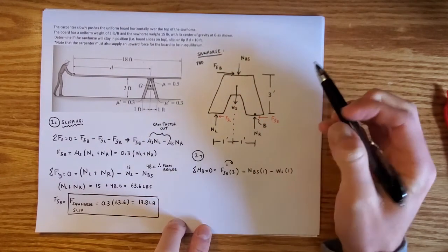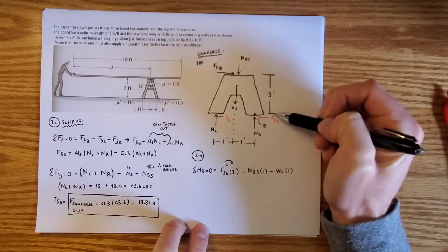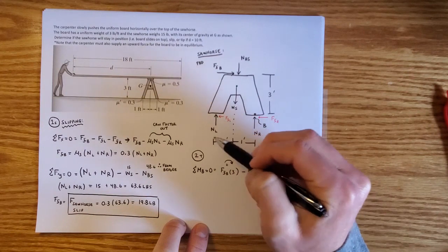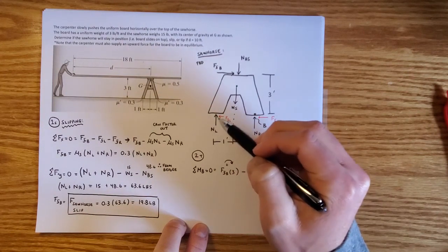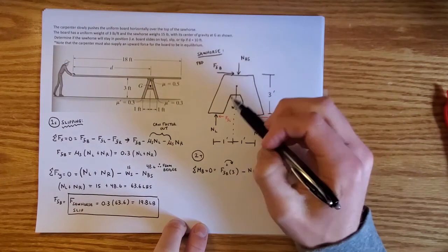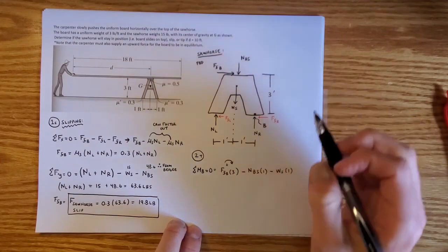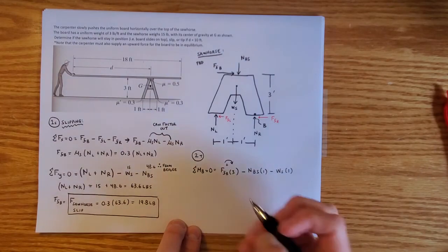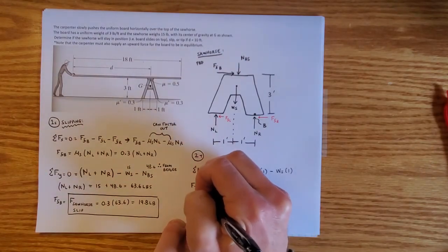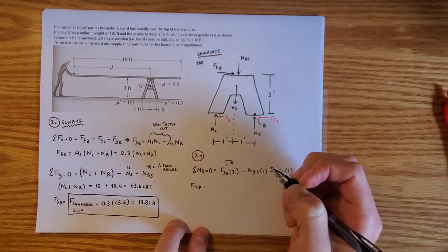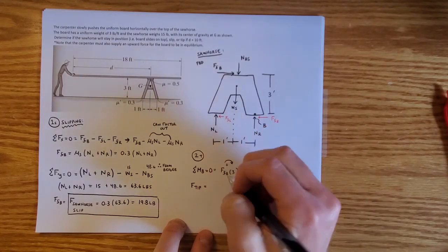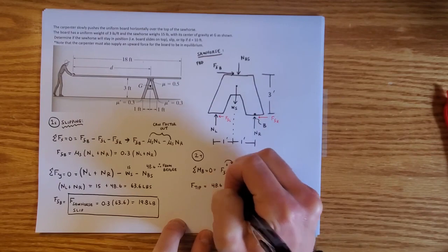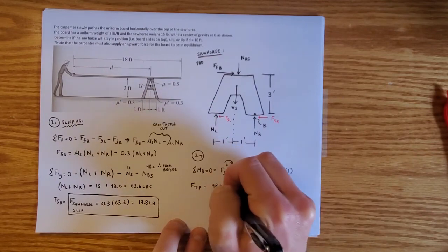Now, NR and the force of friction go away because they pass through that point. And the things over here also go away and are not in our equation because the left leg isn't even touching the ground anymore once it starts to tip. Okay? So we just have this equation right here. So when we calculate FFB, we're really calculating F tip, which is going to be 48.6 plus 15 divided by 3, which is the simplification of what we get from all of our math above.